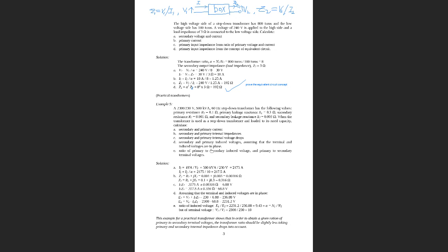In practice, because we are using metal wires, which may be copper wires or other conductive wires, the wires have a resistance. Secondly, the windings have leakage reactance. So the transformer windings have, one, copper resistance due to the resistance of the wire itself; two, the leakage reactance due to the useless flux produced by the current. And furthermore, the core materials may cause core losses. Therefore, there is the so-called core loss. The core loss can be represented by an equivalent resistance.